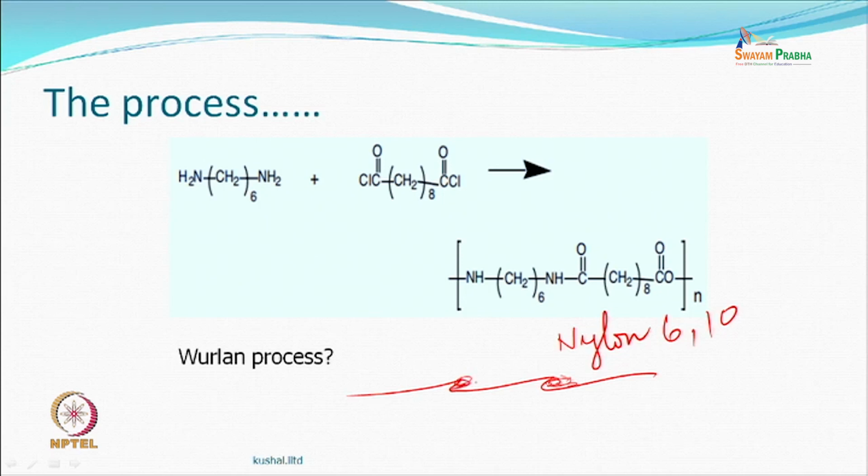So because of surface tension and other kinds of things, the liquid has to go somewhere there. Don't absorb too much. Your aim is that if something goes here, then the friction in this direction and the friction in this direction would be more or less similar. So that directional frictional effect, which is responsible for the movement and the felting, will be taken care of to some extent. There are other polymers also available. So polymer coating is one of the ways in which you make shrink resistant wool. So that's the possible solution.